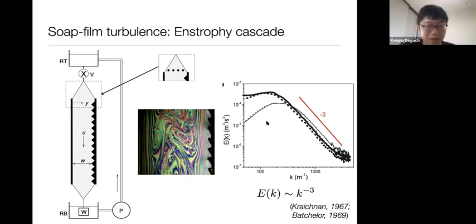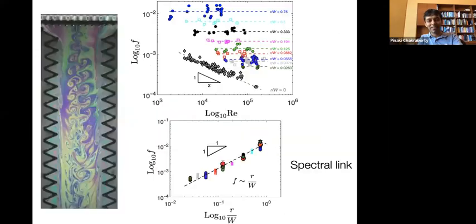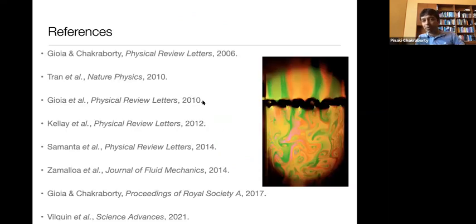Yeah, so this model is really simple and powerful. I guess you consider some more extension. Yes, in fact, if I can just give a plug-in. In this 2010 paper, we actually looked at, and this is related to many of the questions that we've been asked, what is happening when you're going at different distances away from the wall? The mean velocity itself is changing, you have a profile. But the form of the energy spectrum is also changing at different distances from the wall. For one, the dissipation epsilon also has a profile, just like mean velocity has a profile. So the energy spectrum is also a function of y. It's not just E of k, but E of k and y.